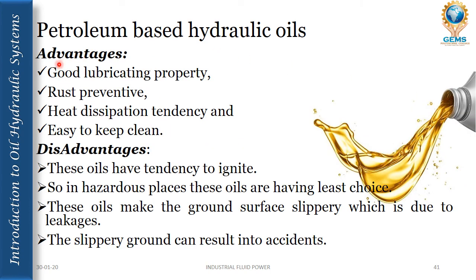What are the advantages of petroleum-based hydraulic oils? They have good lubricating property, rust prevention, heat dissipation tendency, and are easy to keep clean. And the disadvantages are these oils have a tendency to ignite. So in hazardous places, these oils are the least choice. These oils make the ground surface slippery due to leakages. So the slippery ground can result in accidents.